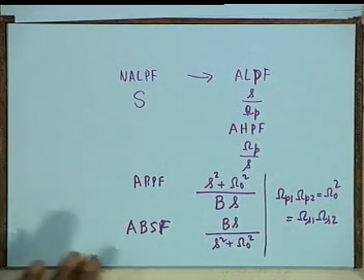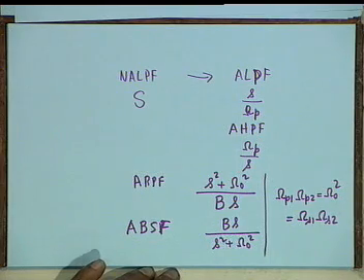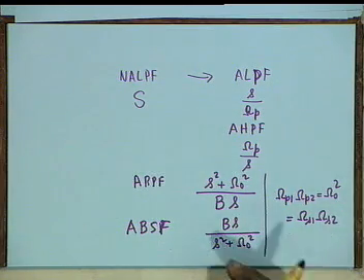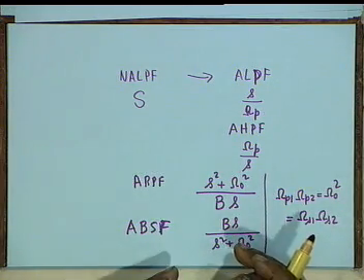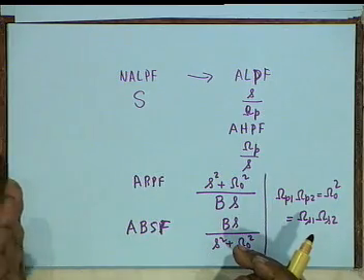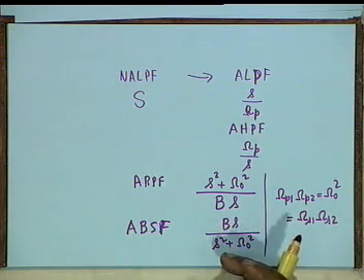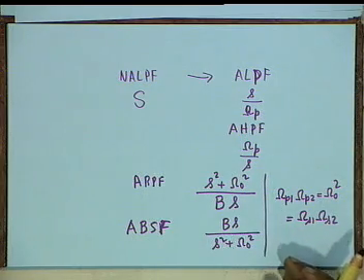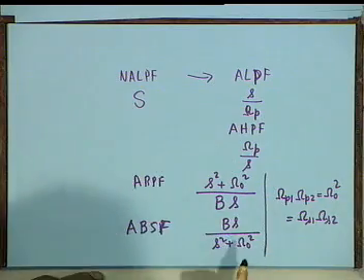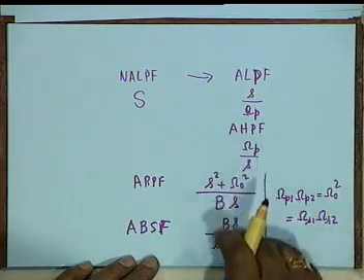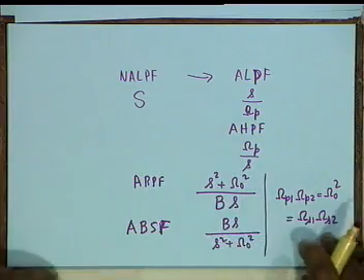Don't do the reverse. Either extend the stop band to the right or extend the stop band to the left. Extension to the left means reducing omega S1. Extension to the right means increasing omega S2. This must be true for both band pass and band stop filters.